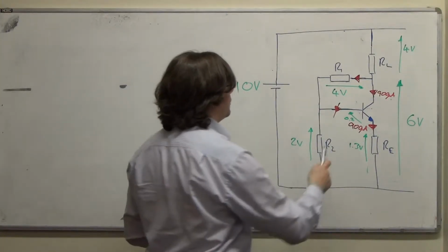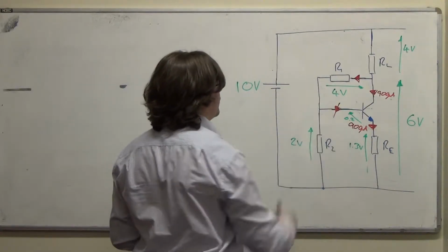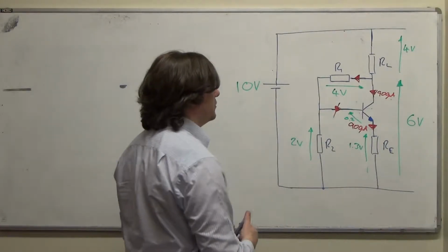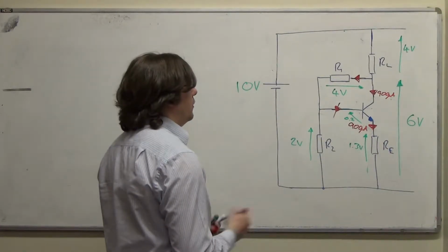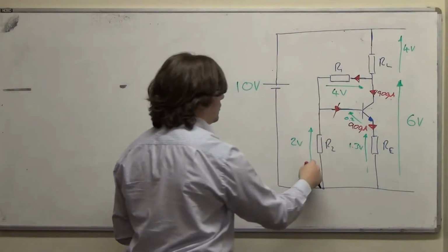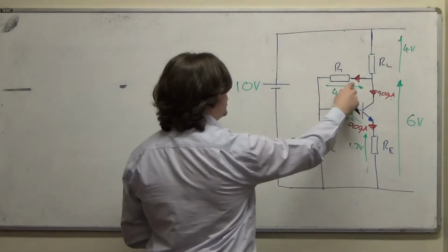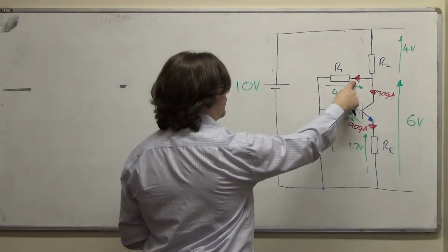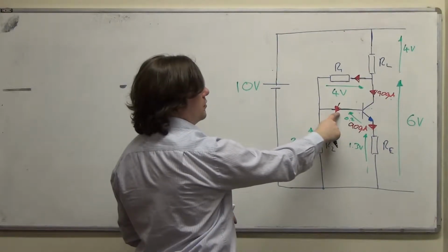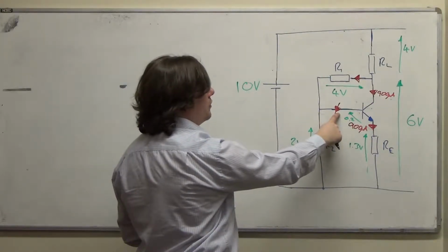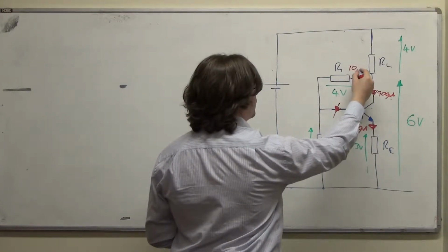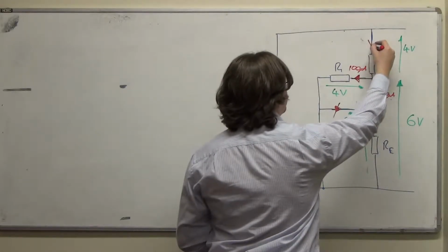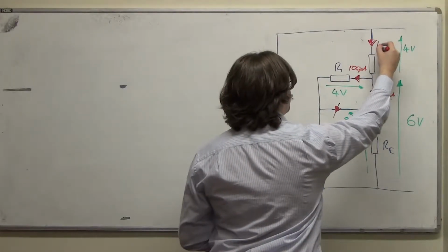And we can either make some choices about resistors and work back to find I1, or we can pick I1 and work out what our resistor should be. I'm going to pick the current. Now, I want R1 and R2 to be quite large, so I don't really want this current to be a significant fraction of this current, but I've got to make sure this current's big enough that the base current is negligible assumption will probably hold. So what I'm going to do is make that 100 microamps, because that means that the total current here will be a milliamp.